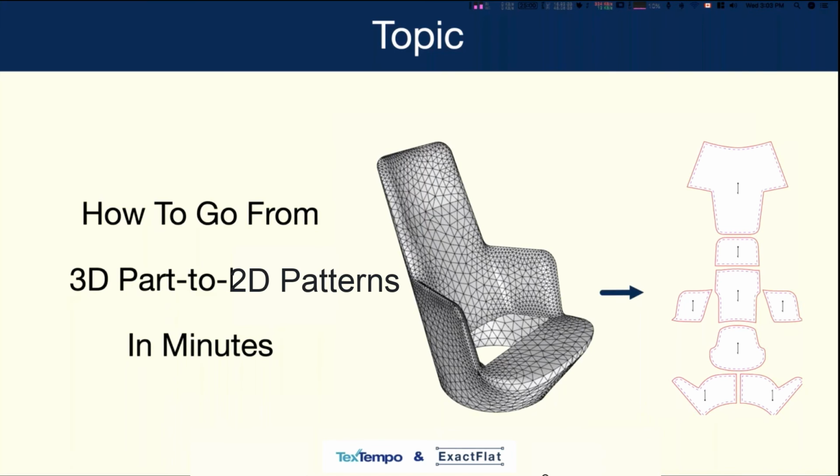So when we do our flattening, we build an internal map based off of the 3D model of which edges are related to one another. That's why when we go to create our seams, we only have to pick one side of the part. ExactFlat will automatically find and place the equivalent seam on the neighboring part. So that's the first part: we have automatic mapping of which edges are related.